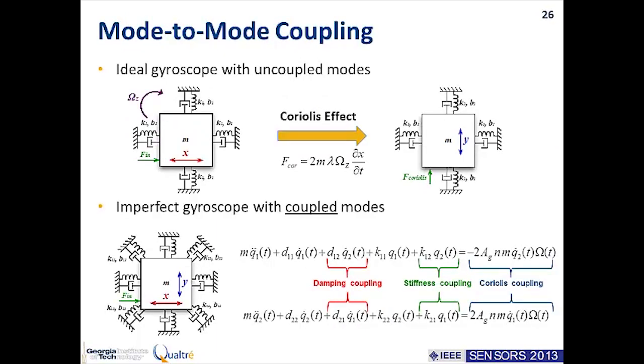What's lambda? Yeah, so lambda is what is known as the angular gain, and we will talk about that when we cover the whole angle mode gyros. So it's basically a factor that accounts for some effects that we will be discussing. It's just an additional constant that actually degrades the amount of energy that couples from one mode to the other, and we'll see why in just a few minutes.